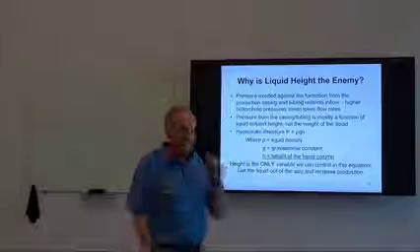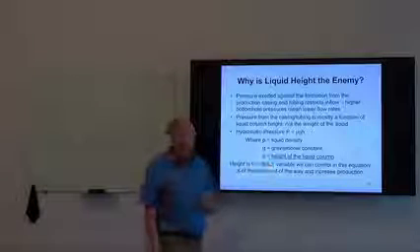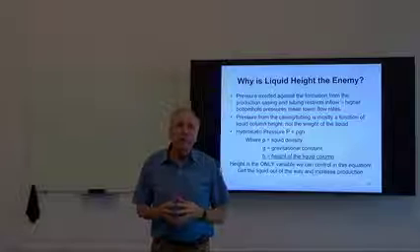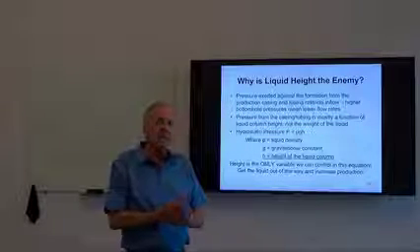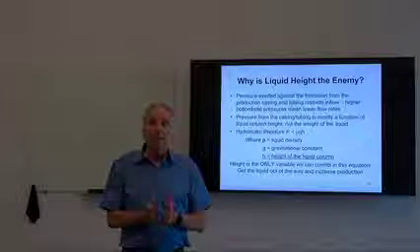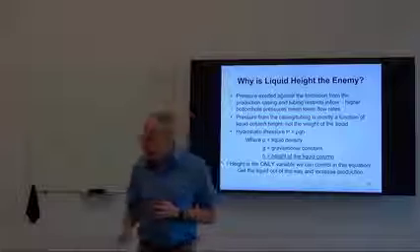And therefore, height is really the only variable that we have any control over, this height of this liquid column. Whatever we do to manage that height of the liquid column is going to be our most effective means in managing production.